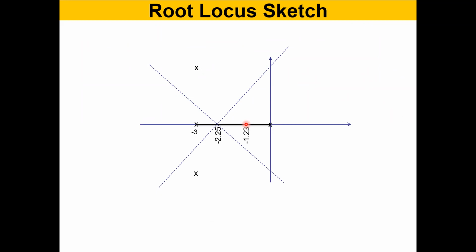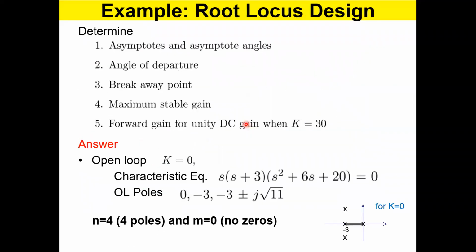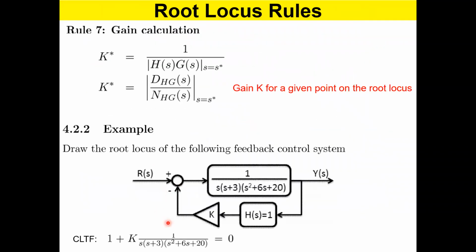If you want to achieve that behavior, you have to set your gain to 31. Okay, so when you set your gain to 31 over here, you get that performance. We have 2 real poles on top of each other. The other 2 poles are anyway oscillatory, right? Because one is up, the other one is below the real axis, right? They are oscillatory poles.